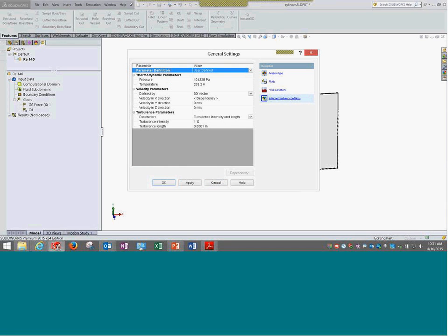Parameters. One important thing, I think this is a default value as well, but we expect turbulence in this case, no doubt, and we are using an intensity of 1%. Now, turbulence is a very big topic, and to understand and explain this is quite involved. But at the moment I would say blindly accept this value and use it. Length as well. That is, we expect the turbulence to be for this distance from wherever it starts. And yes, this is what it is.